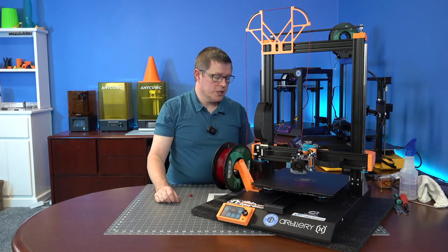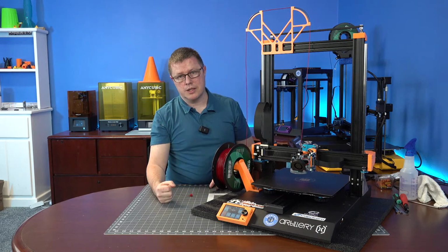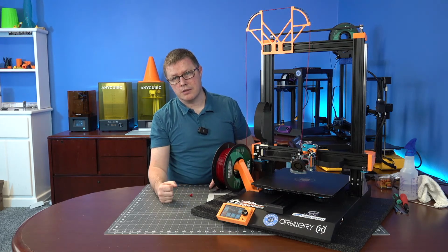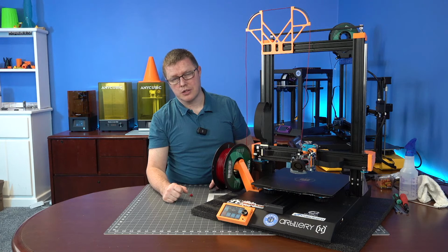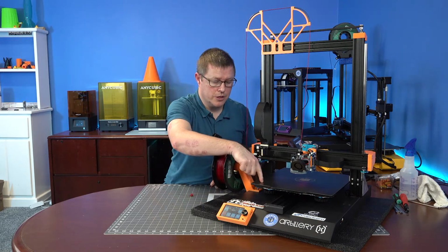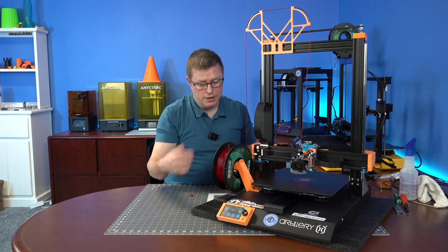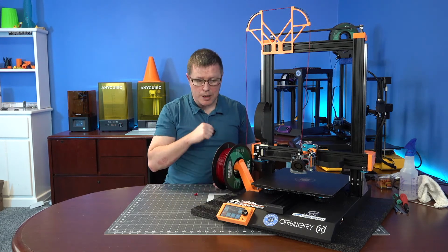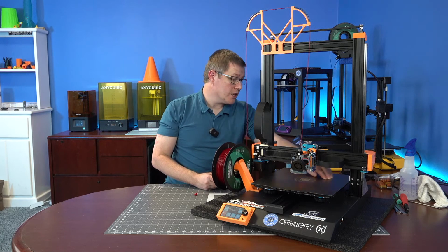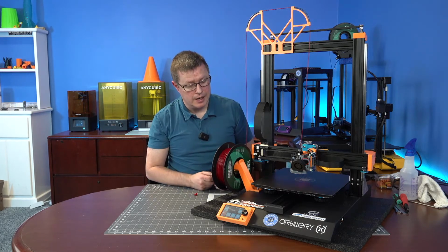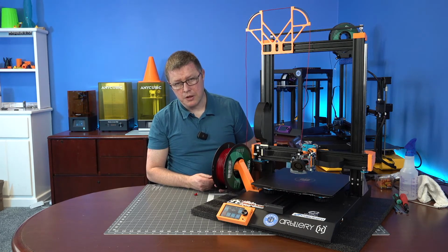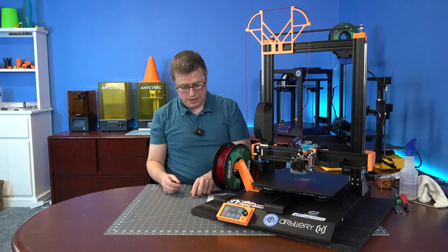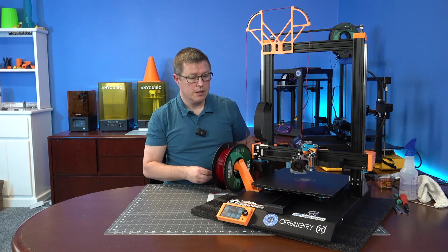I've got a few blemishes on it where I had the nozzle smash into it and stay. I was distracted, and the heat from the nozzle actually melted a little hole in the coating. But it's not peeling or bubbling off from that spot. I've used a scraper on it, and it can definitely be scratched, but it's not like some of the original filament ones where it just peeled off. It's not doing that, which is nice.